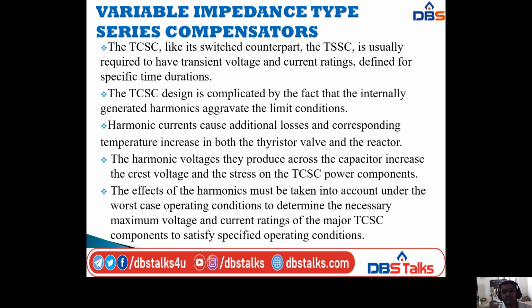The harmonic currents cause additional losses and corresponding temperature increase in both the thyristor valve and reactor. The harmonic voltages they produce across the capacitor increase the crest voltage and the stress on the TCSC power components. So the effects of the harmonics must be taken into account under the worst case operating conditions to determine the necessary maximum voltage and current ratings of the major TCSC components to satisfy specified operating conditions.